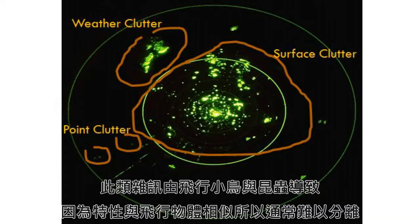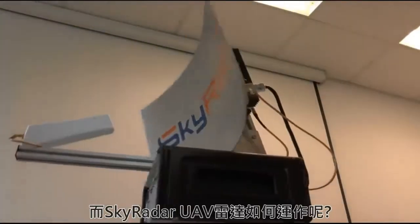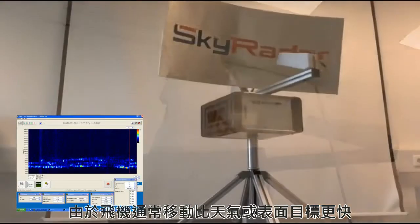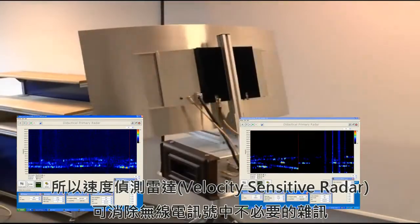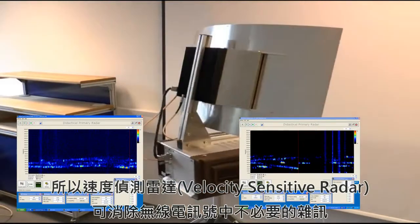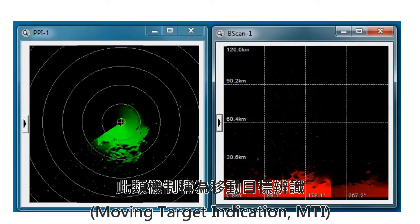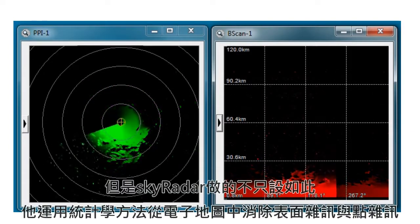Birds and insects produce such a clutter, which is pretty difficult to remove, because the characteristics are very much alike aircrafts. What does SkyRadar do? Since aircraft usually move much faster than weather or surface targets, the velocity-sensitive SkyRadar eliminates unwanted clutter from the radar indicator. Such a system is called moving target indicator. But SkyRadar does much more.